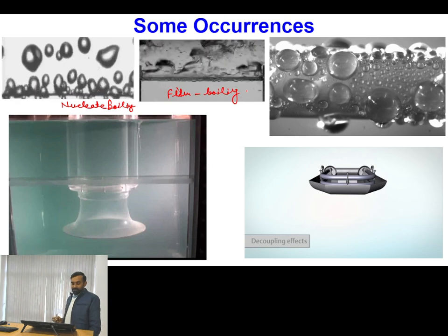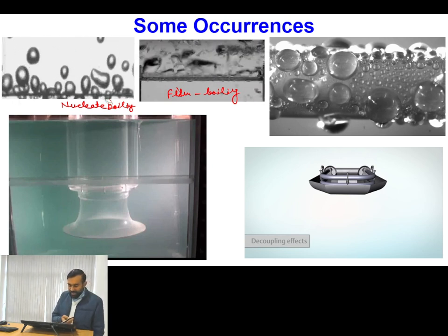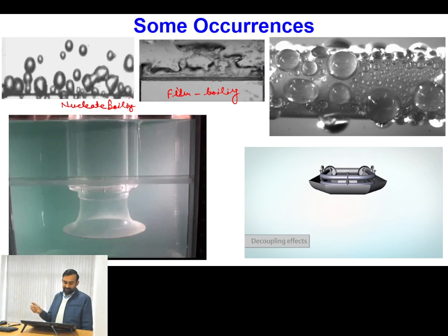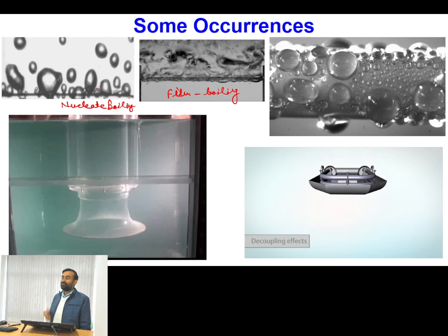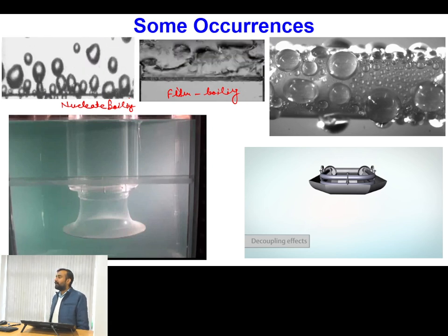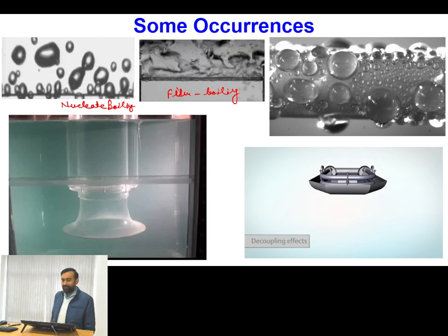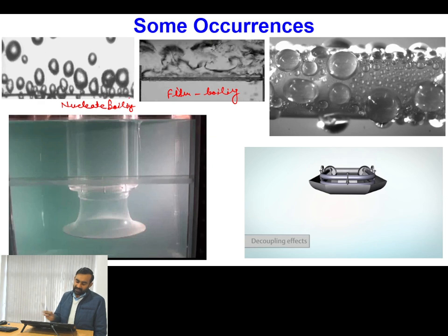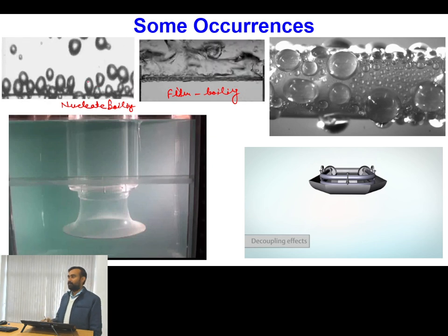Okay, so here you can see that we have some thin wire heater surface. From this thin wire heater surface, if the temperature of the heater surface is greater than the saturation temperature of the substance, and say surrounding liquid is nearly at the saturation temperature condition, then we will be having nucleation of these bubbles.